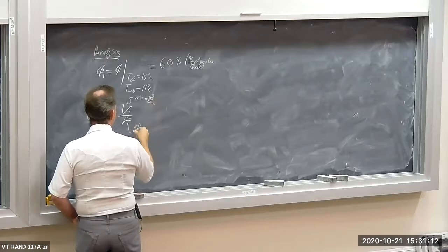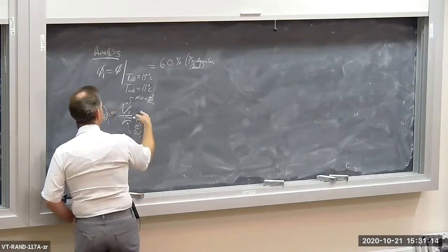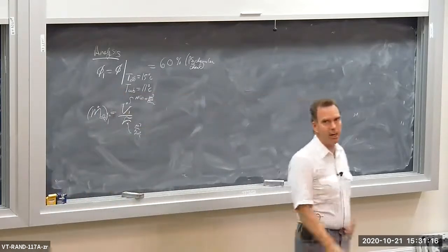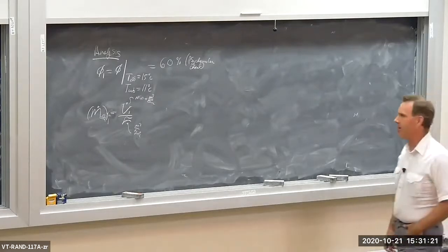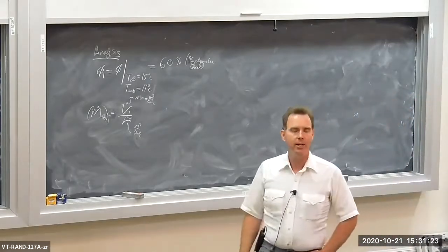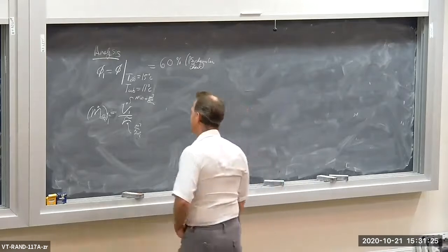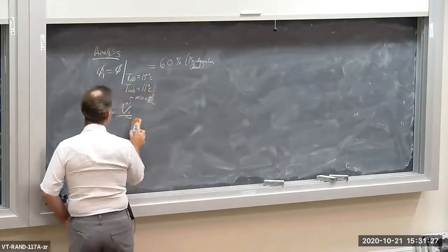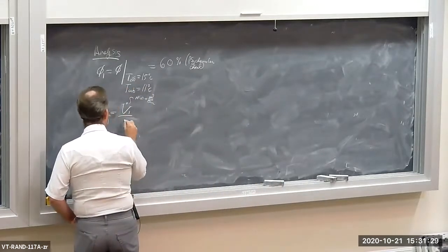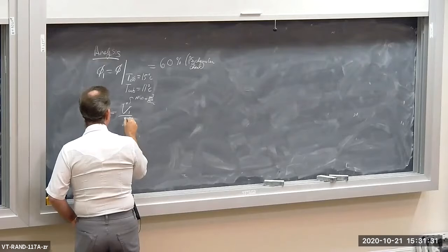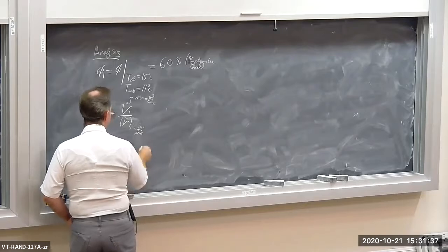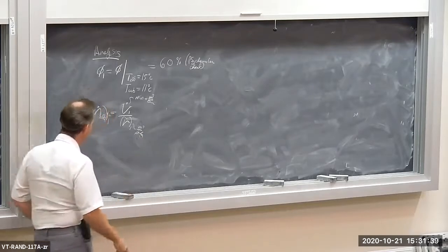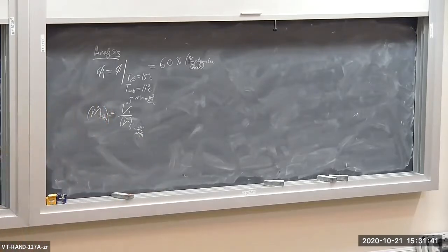The cubic meters will cancel out, and I'll get kilograms of dry air per unit time. So V dot at the inlet divided by V tilde at the inlet, which has units of cubic meters per kilogram of dry air, should give me m dot dry air.